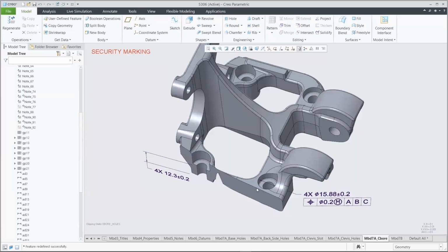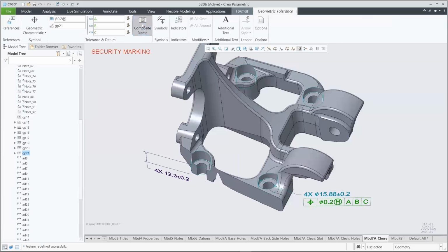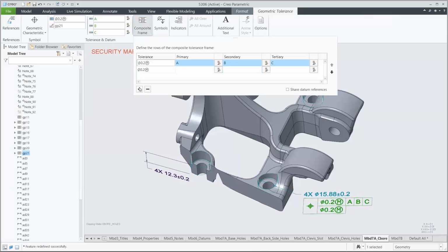So that's one thing to mention here too, is that whenever you're doing your different dimensions or tolerances right here from within the 3D environment, you can get these all laid out and then jump right back and forth between the GD&T Advisor in order to check those, in order to validate that what you're building out is correct. Specifically for any users that are new to model-based definition or GD&T, they don't have to do guesswork. They can be very sure that any of the information that they added in there was correct. And then if there's anything that they didn't understand, it's very easy to go through and get information into that as well.